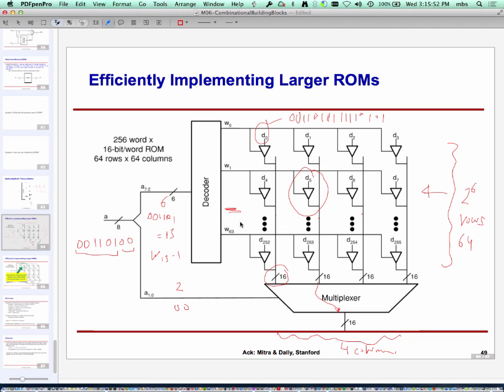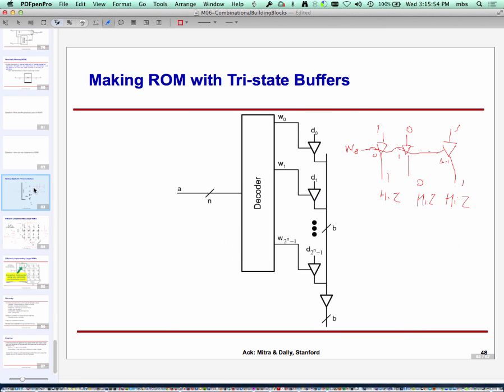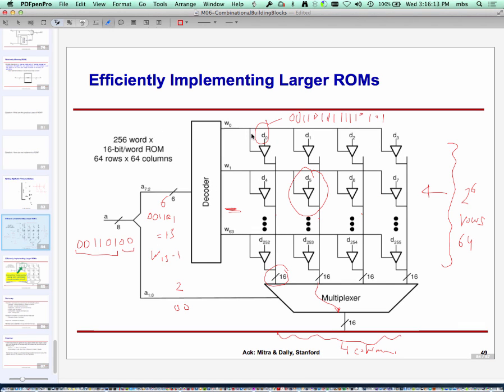In my original type of design, I would have taken all 8 bits of the address and created a decoder, so I would have 256 lines coming out and a single column. That column would run over a long distance, and I would have a huge decoder. Now I have a smaller decoder, and the total number of wires is 64 plus 4, 68, as opposed to 256 plus 1, 257.